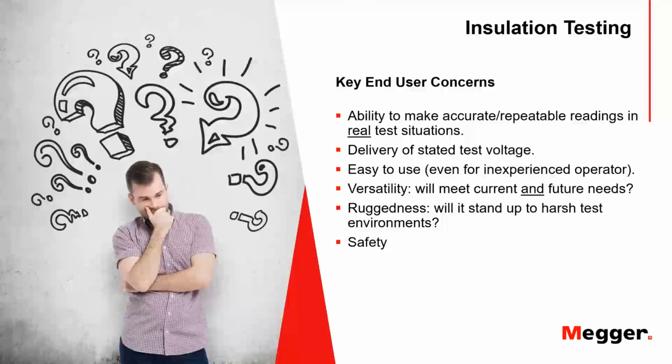Okay, so these are things to think about when you're purchasing an insulation tester. If you're only going to do spot go/no-go type testing to reach a standard, or to spot a piece of equipment that's shorted out, then you don't need a whole lot of complication and extra features on your tester. But on the other hand, if you are going into more sophisticated testing and you're purchasing a tester, then there are various things you want to look at and make sure that they're in line with your needs. Next.